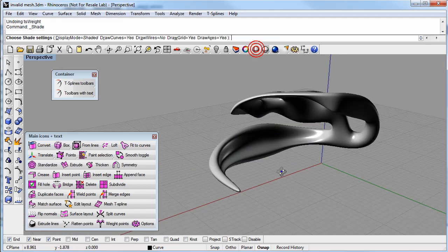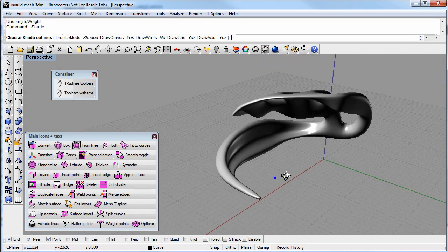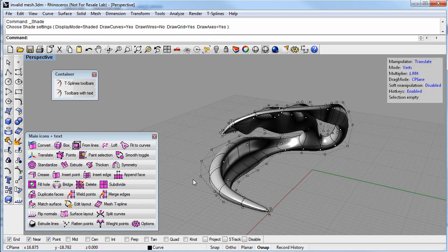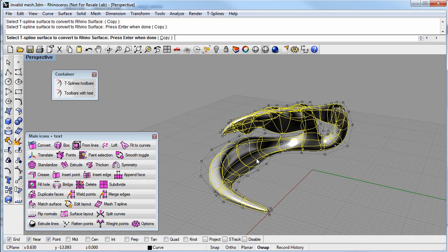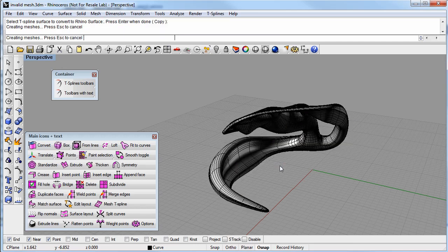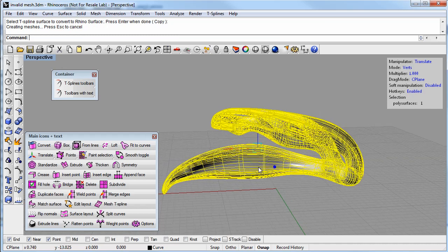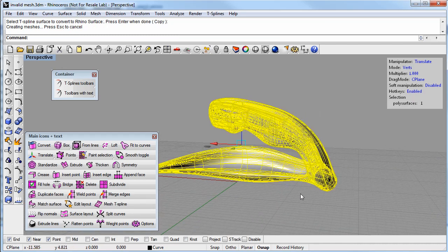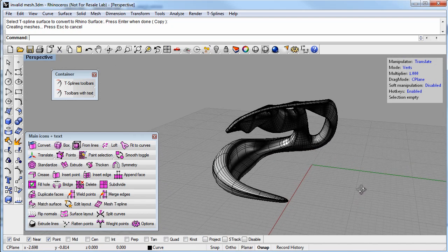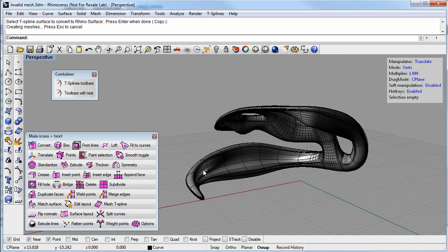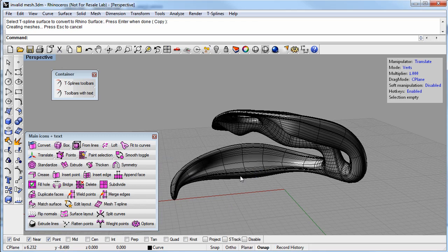So finally, we can just convert this to NURBS to do any other operations that we need to do. And converting from T-Splines to NURBS is just a push button operation. Just right click on here, click on the T-Spline, hit enter, and you can see here all of a sudden this is just a Rhino poly surface, exactly the same shape as the T-Spline surface. So those are just introducing some T-Splines commands and ways that they can be used to make a freeform architectural form.